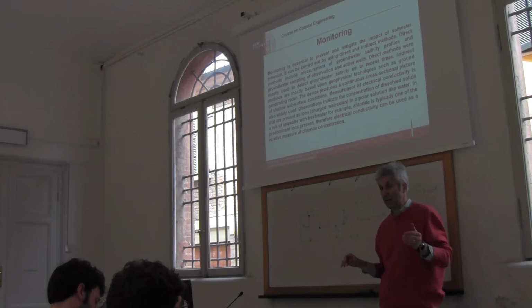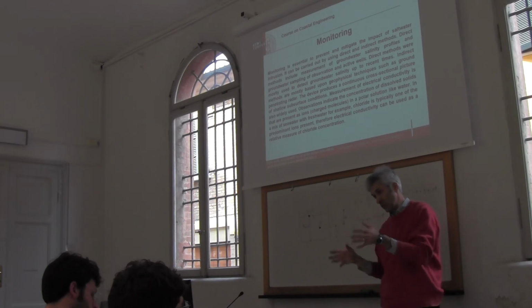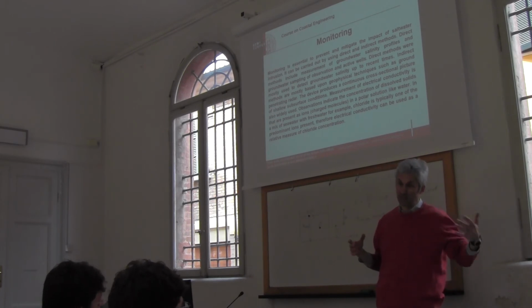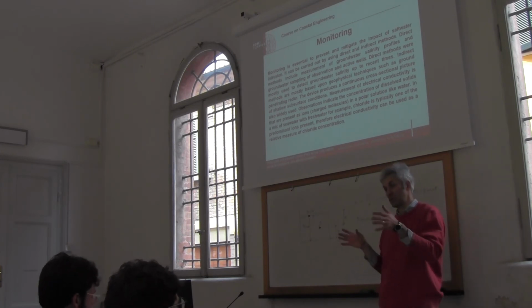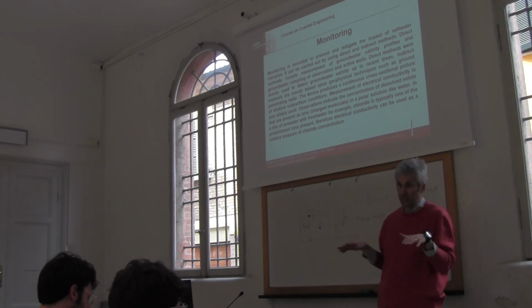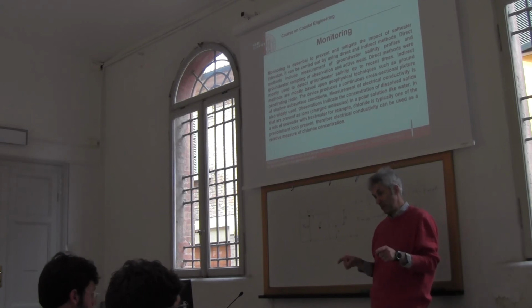They can be actual wells, meaning that they are the sources, for instance, of fresh water for water supply systems. So while you pump, we observe the water that we pump, the water flow, and also we observe the water level in the well. And also we measure salinity.